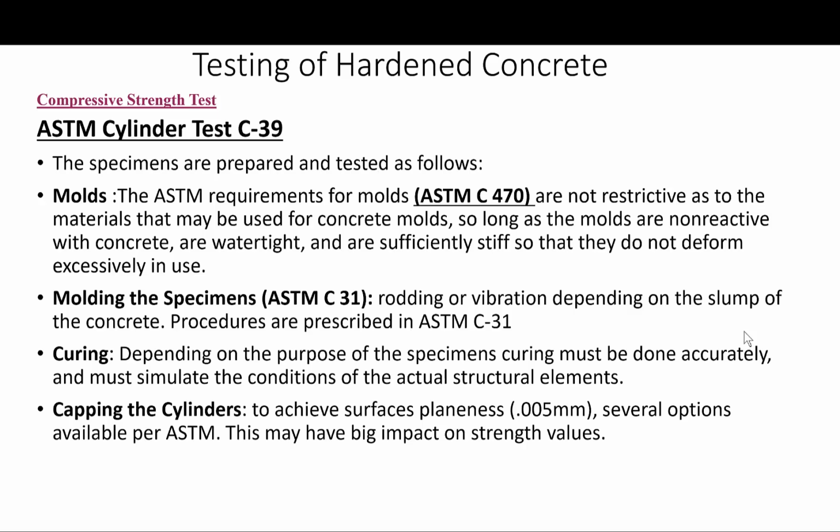So basically, the selection between single-use molds and reusable molds goes back to the concrete practitioner and his experience. But as I said, care must be taken when dealing with high-strength concrete. Reusable molds should be avoided.